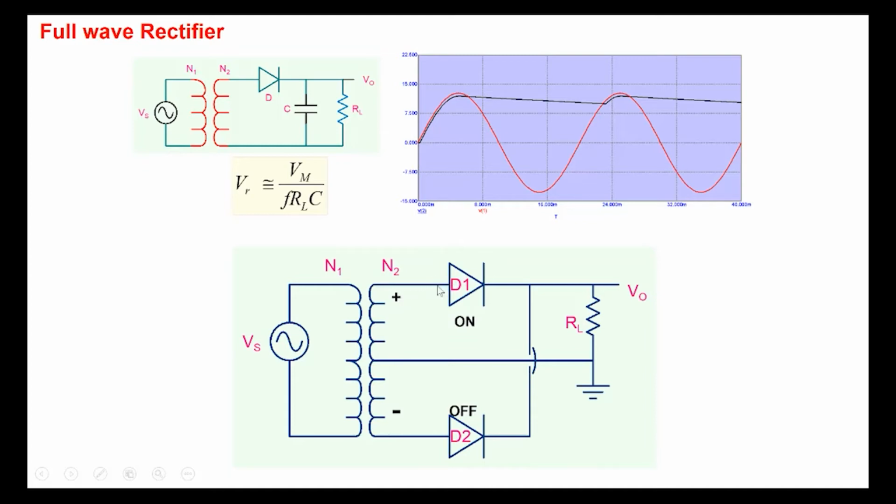If you look at the circuit, positive here, D1 here, through RL and then to the ground. Because this positive voltage is sufficiently high compared to the diode drop, the diode D1 is on. And this is the direction in which the current would flow. It would start from here, flow here, and of course go through RL in this particular direction.